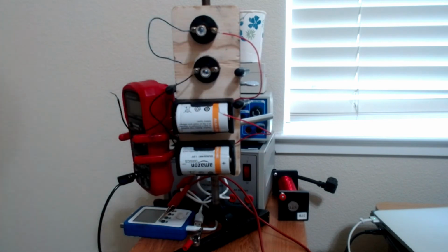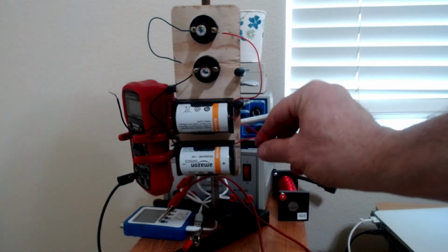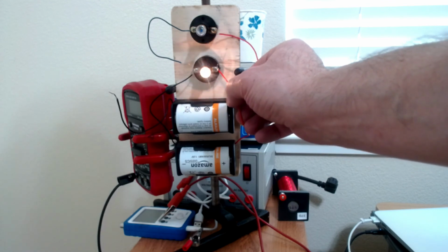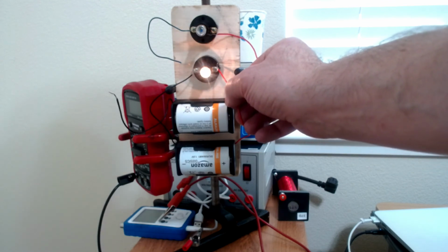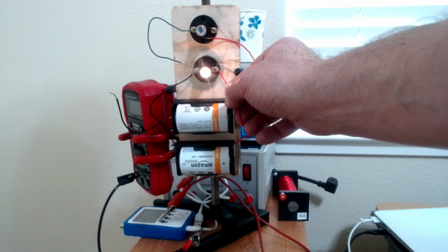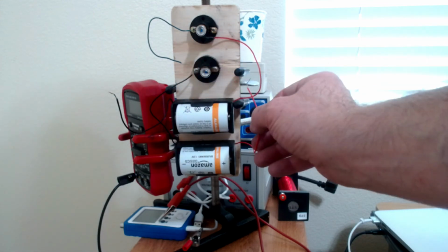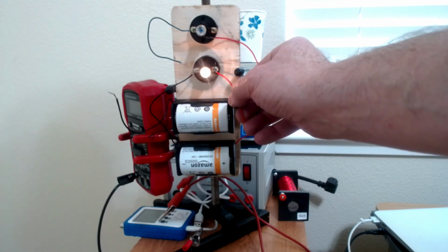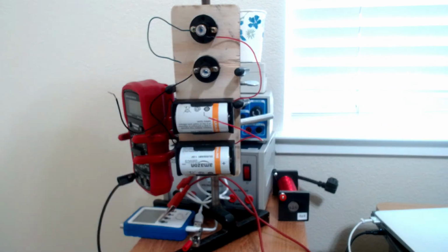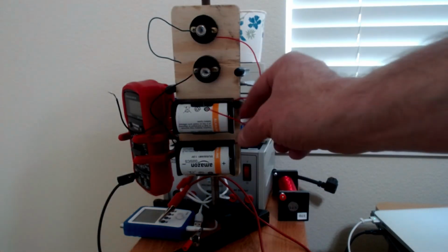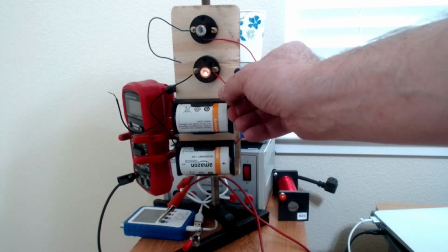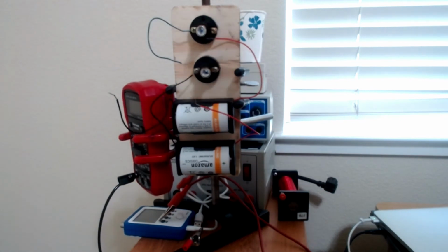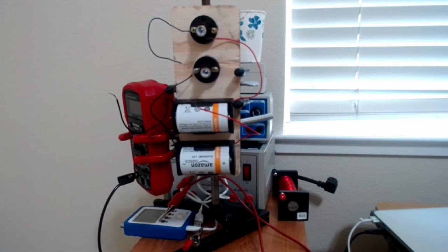So I'll put that in, and then on the other side, I'm just going to do it by hand. The other side goes to the other side of the bulb, and you see the light bulb goes on. And you have to have a complete circuit. The electrons have to have a closed path to go all the way around, because if not, the light bulb will go off. That's a simple circuit. And if I were to measure the voltage across the bulb, it'll probably be different than the voltage from the battery because of the internal resistance in my circuit.